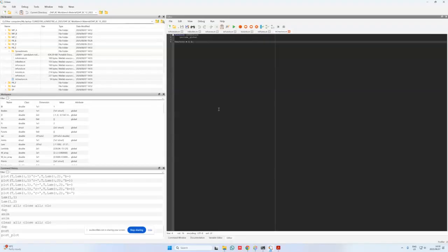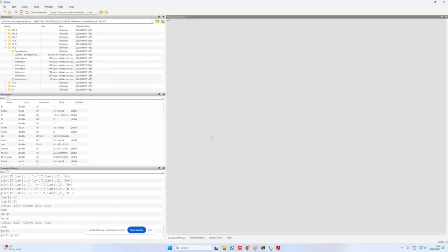The important thing to note over here is I now have two combined dynamic analyses that I'm running. I'm providing a constant torque on the system, but I'm also providing a driver constraint which limits the angular acceleration of the system. So let's now see what happens to the results.